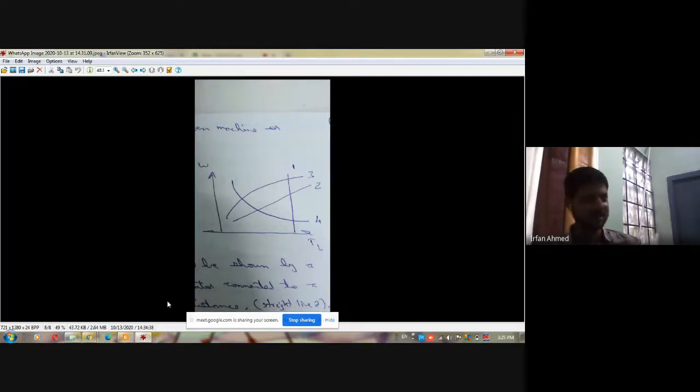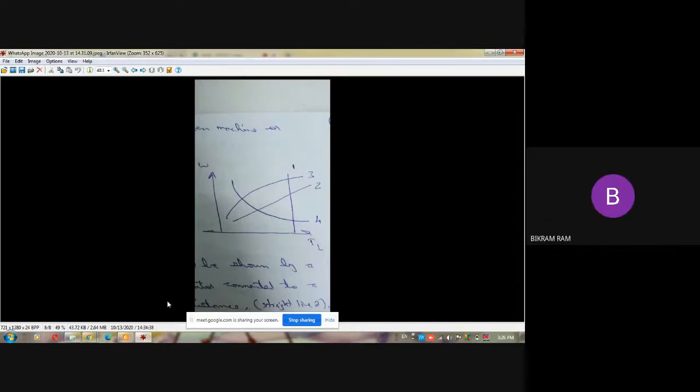We just saw that friction torque is directly proportional to the speed. So at that low speed, friction is negligible. What is the major component? It is the torque required to do the useful work, and in the case of a crane that is heavily dependent on the gravitational force. Does the gravitational force change with the speed?